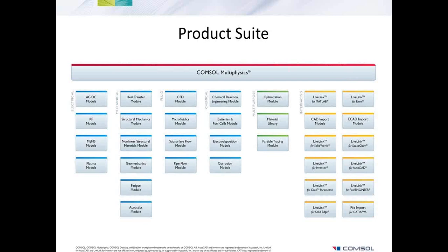the acoustics module. Okay. Here's a question that comes from Hugo, and he says, is it possible to simulate coupled transducers in a water medium? For example, if you wanted to send signals from one transducer to another, taking into account reflections. Yes, absolutely. That's very straightforward. It's exactly what I did in the demo problem. It's just that you need to add a second transducer in your model. That's all that you need to do.